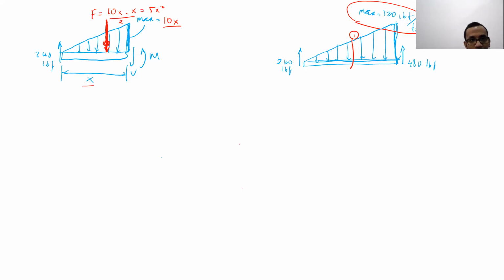I understand. Okay. Now, because I draw the final free body diagram, I can represent it with a concentrated load like that. Okay, Darian? And the concentrated load is supposed to be located at what location? 2/3 of x. Yeah, 2/3 of x. Or if we use the right side, it's supposed to be x over 3, right? Darian? Yes, sir.